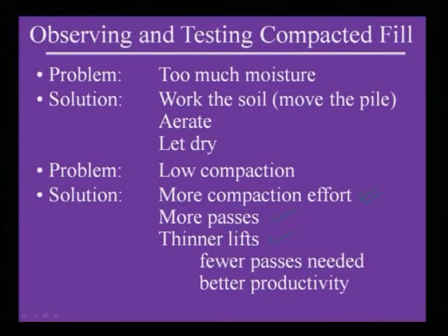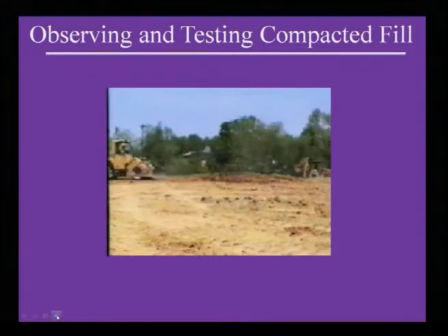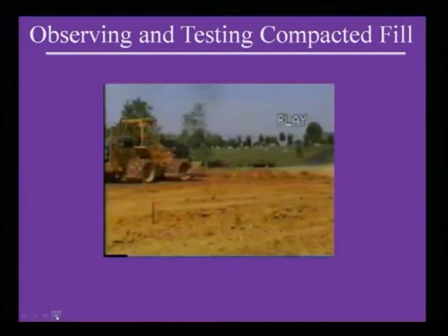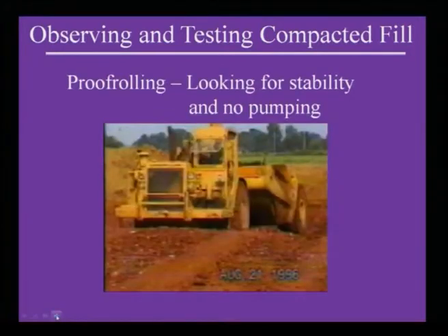Fewer passes needed, better productivity. Look at this, observing and testing compacted fill. This is a ground, how it has been compacted. If you look at here, how it has been compacted by means of roller. Then look at this proof rolling, looking for stability and no pumping.